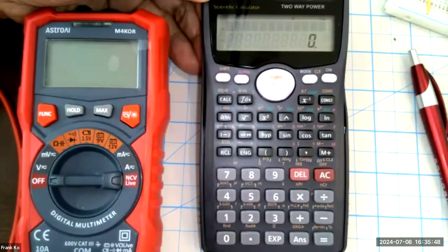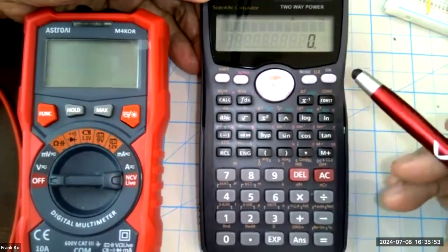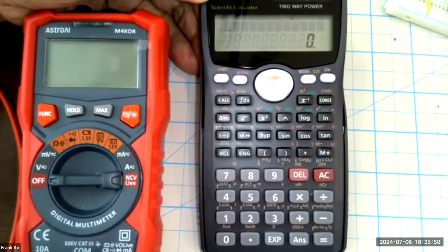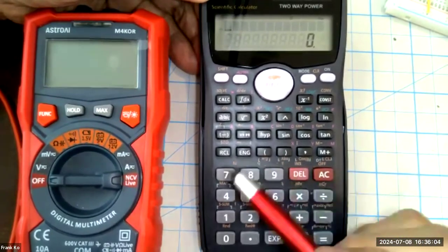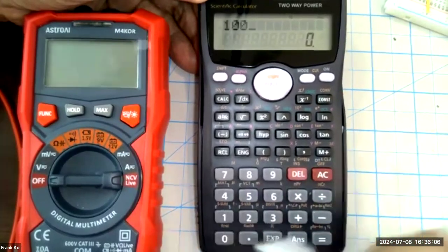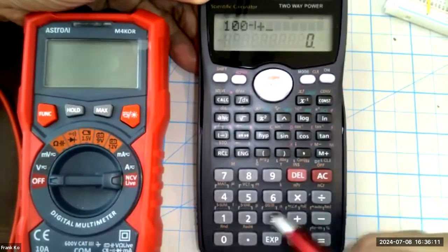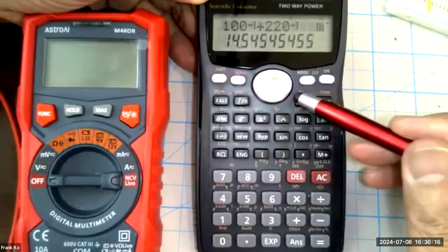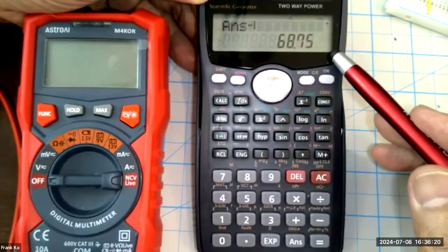All right, so now let's go back. We are now onto the calculator, and your task, you copied this into your journal so you know what the task is, should already be written in your journal. You were tasked to calculate R1 parallel with R2. R1 is 100 ohms, so clear 100, hit your reciprocal button, add 220, hit your reciprocal button, hit equals, reciprocal equals, and I calculate 68.75 ohms.